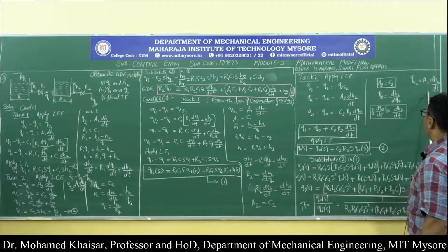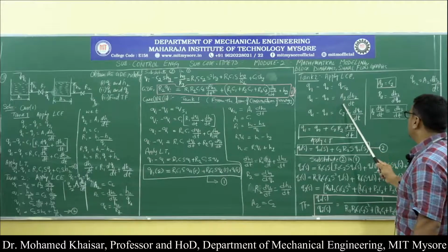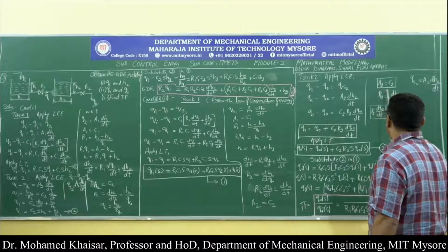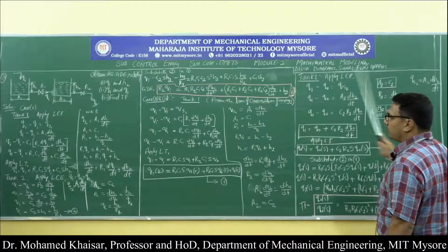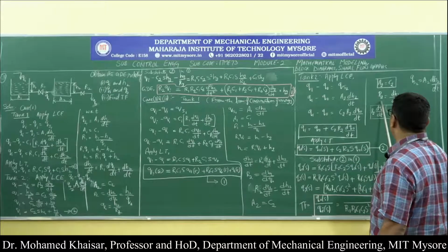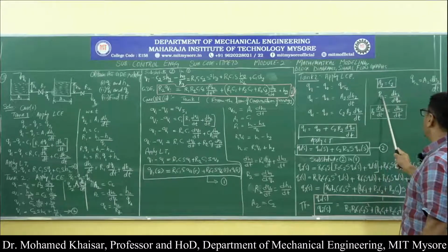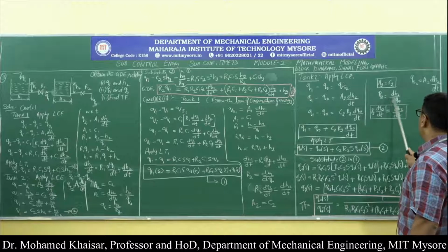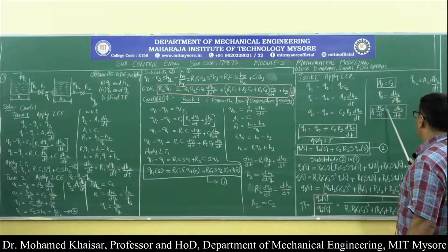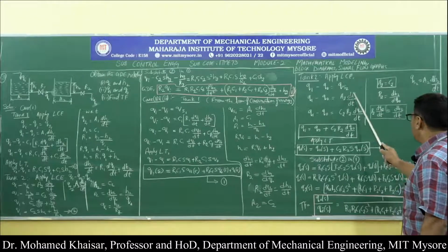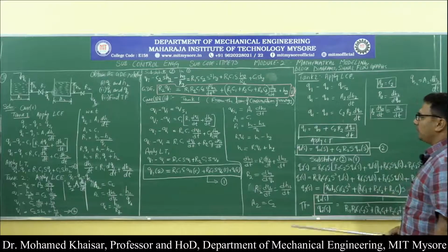So, when we know this, we will replace QS2 by A2 into dH2 by dt. Then Q1 minus Q naught will retain. A2 is nothing but the hydraulic capacitance of tank 2, that is C2. R2 is equal to dH2 by dQ naught, we know that. Then you just cross multiply: R2 into dQ naught is equal to dH2, divided by dt, you will get R2 dQ naught by dt is equal to dH2 by dt. That is what you will be replacing in place of dH2 by dt.